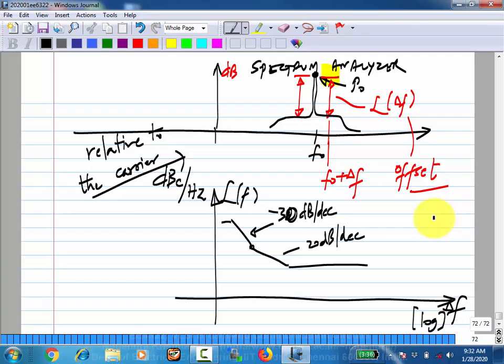So we have noise in circuit components like MOS transistors and resistors, also bipolar transistors. From that you can calculate the voltage noise or current noise in any circuit. Similarly, you have phase noise with periodic signals, that is, signals that are not exactly periodic. From there you can find the jitter variance from the spectrum of the phase noise. Any questions about anything we have done so far?